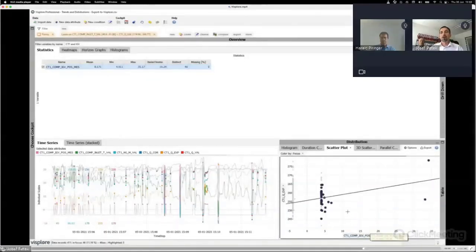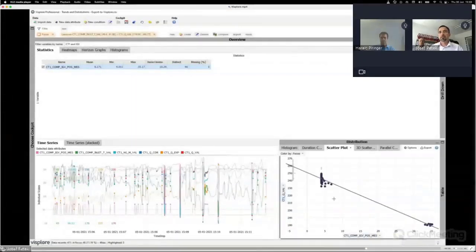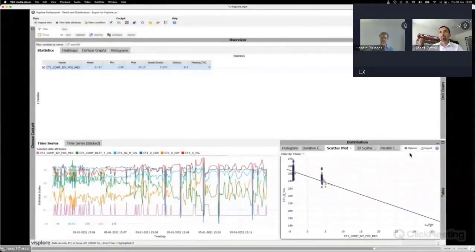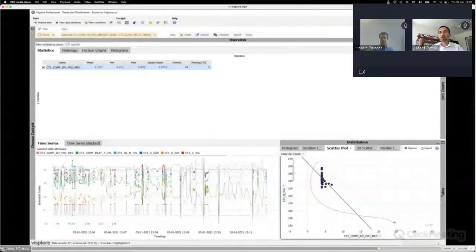And if we look for power output over IGV angle, then unexpectedly, we see that there is not just one full open position here. Actually, there are 3 levels of IGVs, and those 3 levels also correlate with power. So we probably have found the reason for the data situation that we see here. And in order to prove that the IGV is the reason for the outsticking data points, we redo the selection now based on IGV angle.